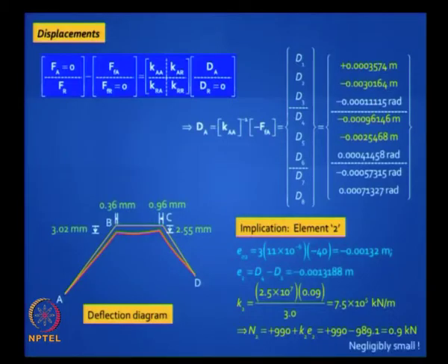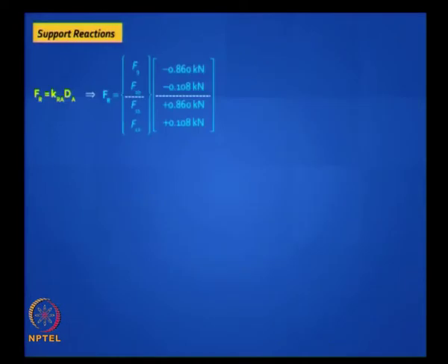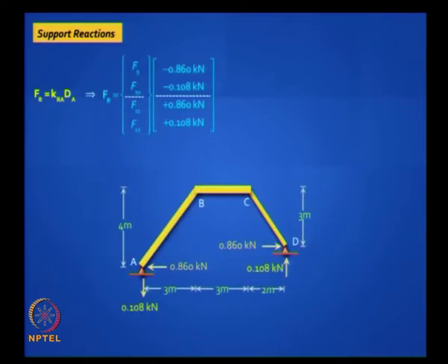The next step is, here you find the force is negligibly small, and you find out the support reactions. The support reactions also turn out to be very small, not surprisingly, and it's self-equilibrating. Look at that. There is no load on the structure, you cooled the structure and you got support reactions. It's just self-equilibrating. There's no external direct loading acting on the structure.